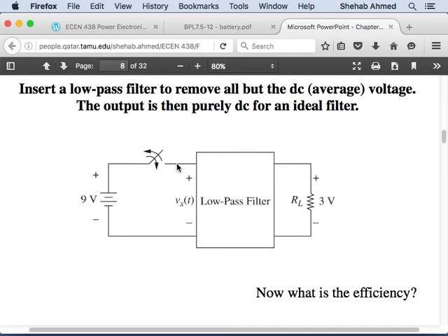You will bring this peak down and spread this waveform over a longer period of time. So you will have the same RMS value, which represents the amount of energy you have in the waveform, but you will relax the requirement on the switch. The switch will no longer have to see a very peaky current. It will see a lower peak spread over a larger period of time, which is what they prefer to see.